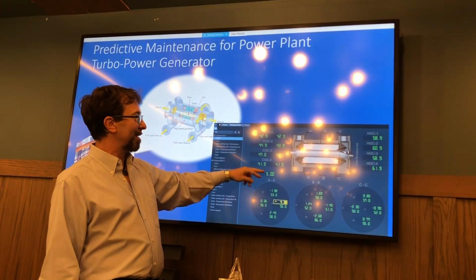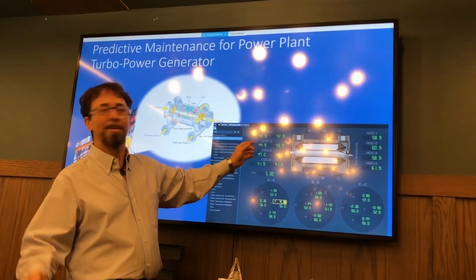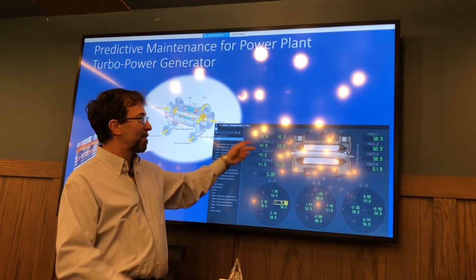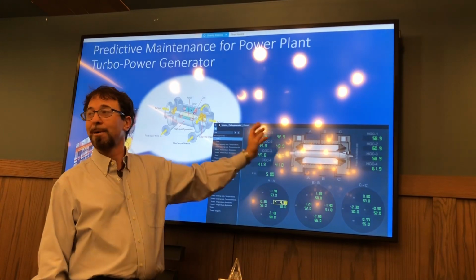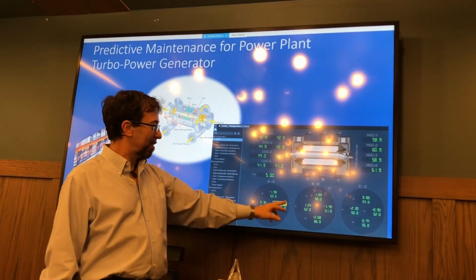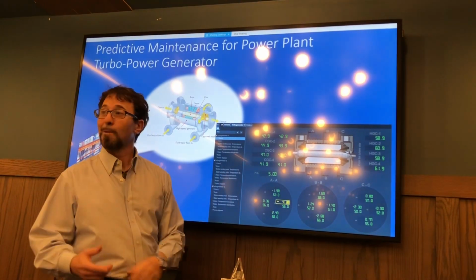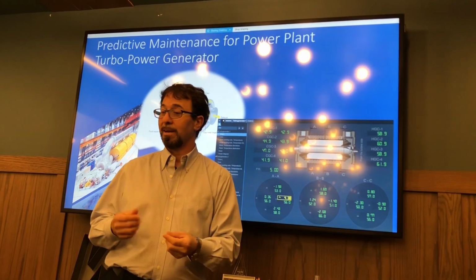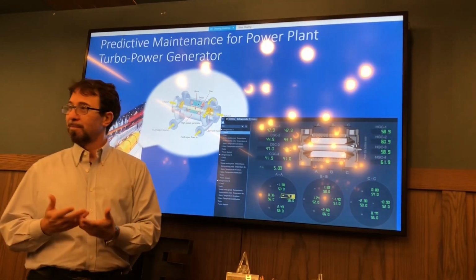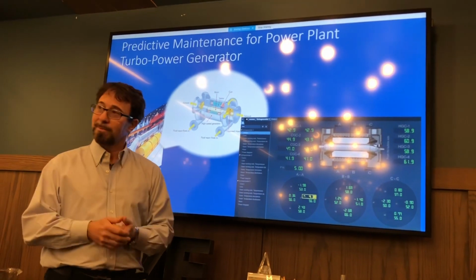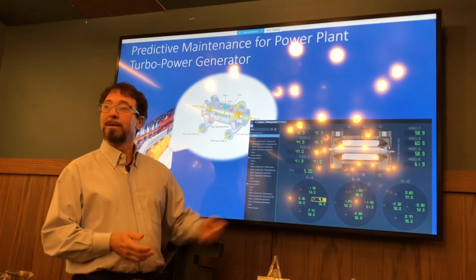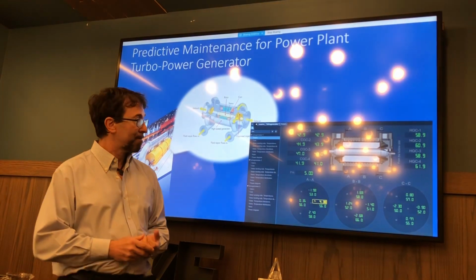and you can look at other data, the voltage and the power going through. Then you say, for this voltage, amp, and power going through, the temperature here is an anomaly. This means that there might be some windings losing the insulation and overheating. There are many things that can happen in this world.